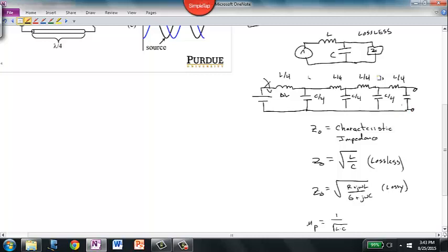Older engineers, if you're working out in industry, a lot of times called this surge impedance. And this is because if the source is a DC battery, as we've shown in this example, to the battery, while the signal is moving down the transmission line, a constant current draw is seen from the source, and so the transmission line looks like a resistor. It's the current being drawn into these capacitors. So there's a constant current draw that isn't actually related to the load. Once the signal has reached steady state and all these little capacitors have been charged, the battery no longer sees this impedance and the surge has ended.